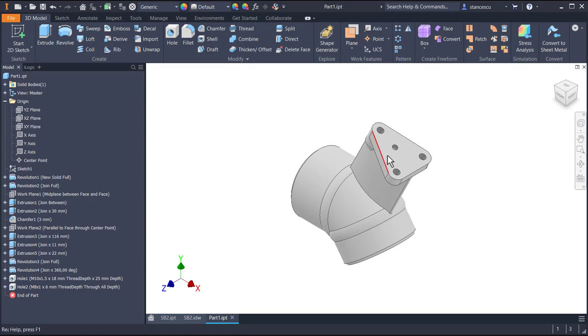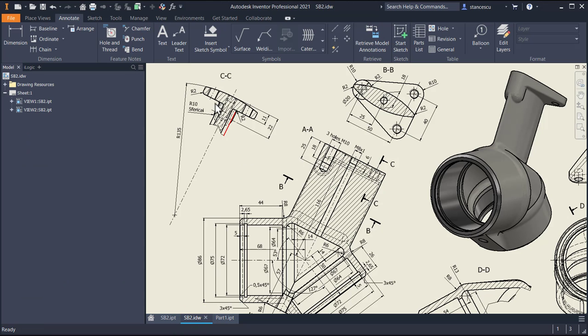good. Next is the cylindrical face here. You see, cylindrical with a radius of 135 millimeters. So we have to create an axis here at this distance from the face.